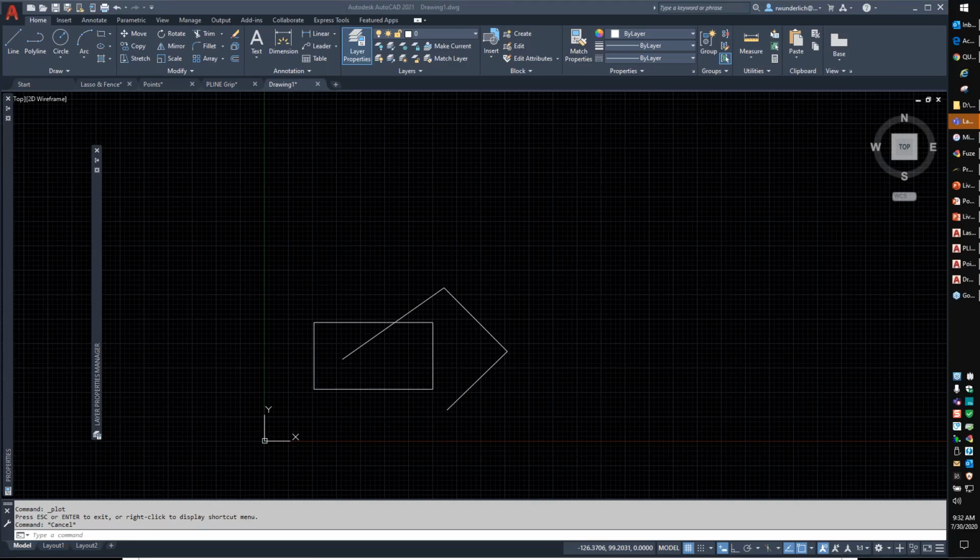Shannon, have you done embedded spreadsheets in Excel? So my question is going to be, are you copying and pasting as an OLE object, or are you using the data connection wizard to actually open up the spreadsheet, bring it into AutoCAD as a data link, so that if you modify the spreadsheet, regardless of whether or not AutoCAD is open, next time you open up AutoCAD, that spreadsheet automatically updates? That's going to be the question. So I will wait for her.